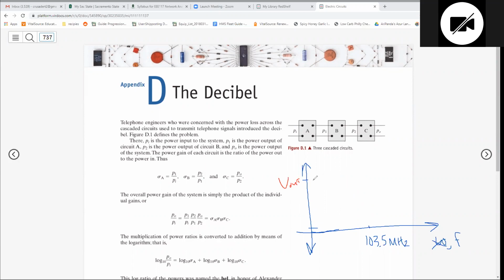Well, if you have a subwoofer, you want to make sure that you only let the low frequency stuff through. So what you'll do is you'll put a filter up to maybe, I don't know, 150 hertz, right? Anything below, you're going to want to let the voltage through and let the subwoofer work. Anything at a high frequency, you don't want it to operate. So again, we can make a circuit, a filter to do this. Another thing people like to do is filter out high frequency noise.